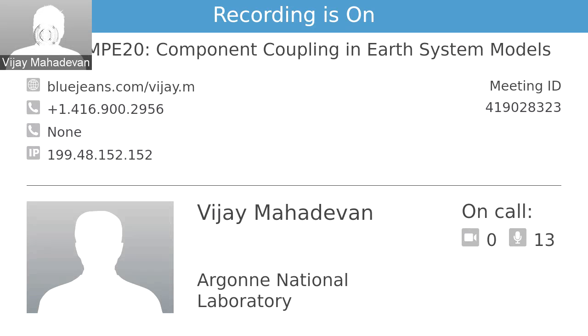Chad, I have a question. Sure. When you talked about using non-matching grids, I know you mentioned mortar finite elements to do the transfer, right? Essentially, you have a Lagrange multiplier that you also resolve as part of your solver. Is that so you can realize that flux at the interface, that auxiliary variable, it takes the place of that Lagrange multiplier. So this transfer, this mortar transfer, happens in the third equation.